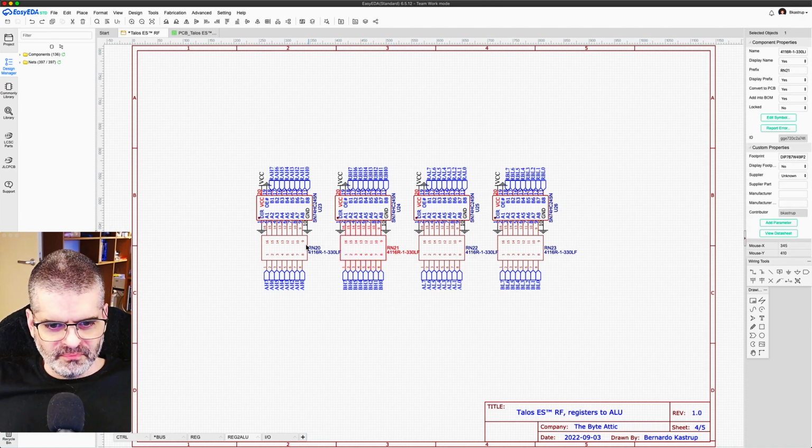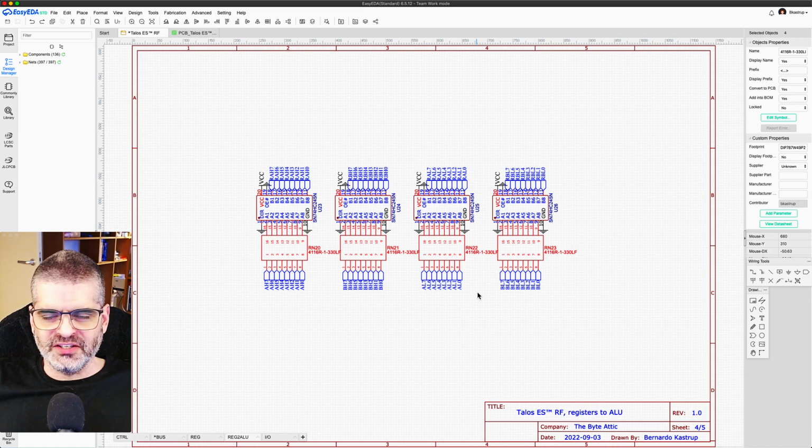And in the case of the flag signals of the ALU board, my concern is not impedance matching with the PCB traces. My concern is the reflections from the backplane connector. And if that's the concern, then it doesn't matter where you put them. Anywhere in the entire net, the filter will absorb the reflections, whether it's on the driver end, the receiver end, before or after the backplane connector. If I put the filter on the receiver's end, there will be reflections on the driver end, but it doesn't matter because the receiver will not see it anyway.